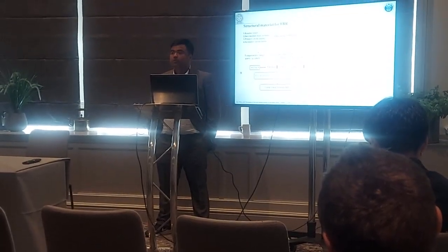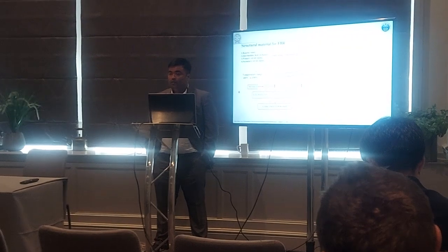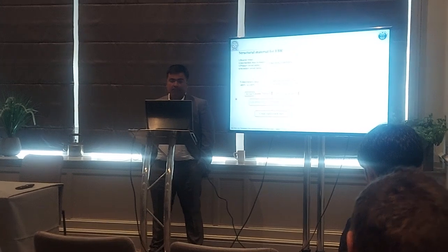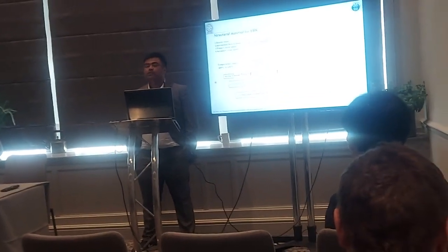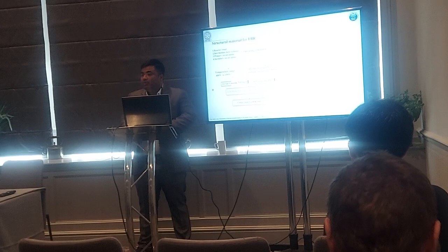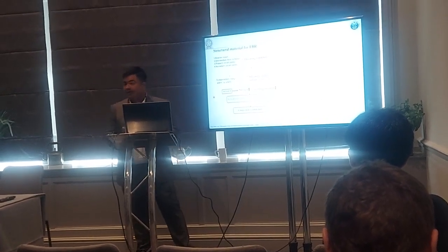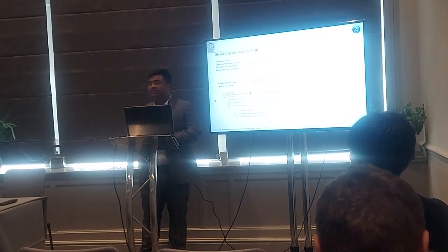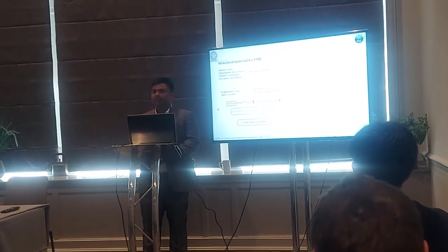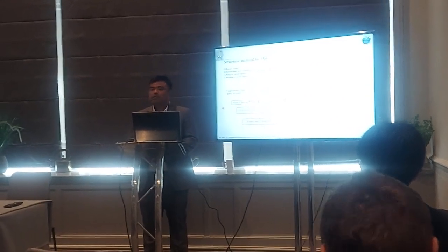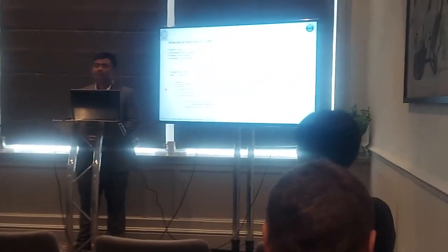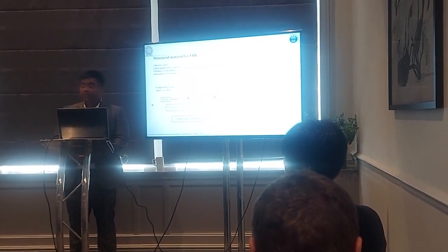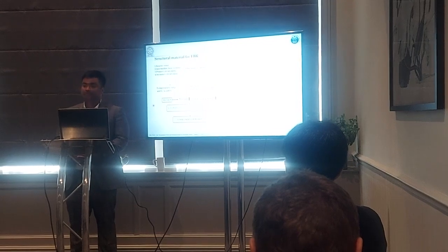Creep crack growth is a technique for this. Why is it important? Suppose the material is operating at a high temperature, so there is a chance of diffusion domination, vacancies are created, micro cracks form, and this leads to cavities and cracks in the system. Sometimes cracks also come from manufacturing defects. So if any component has a crack and its working condition involves time dependent plastic deformation, that is a creep condition. So creep crack growth study is very important for that condition.